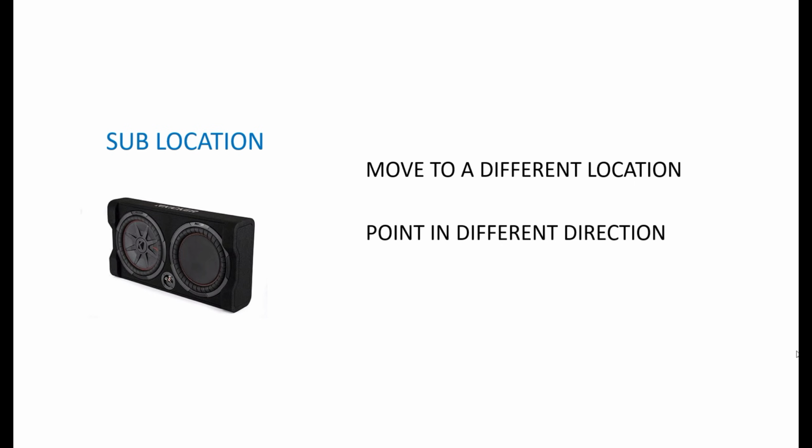Now, people ask, what's the best way to aim your subwoofers? And that's a difficult question to answer, but generally it's better to aim your subs towards the rear of the car, because the sound will reflect off the back of the cabin, and it will load the interior better, right?